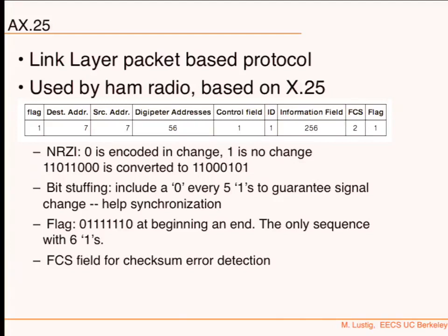For the FM1, we're using a bandwidth of 1.2K, so 500 hertz on both sides, plus the bit rate. So you're using about 2 kilohertz of bandwidth. I was thinking when we first built the filter, I was trying to use 500 hertz on both sides and modulate the frequency to 1.7K. But that doesn't really give me the right thing. So I have to use the low pass filter of 1.2K first, and then modulate to 1.7K.